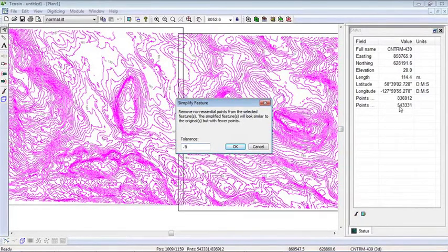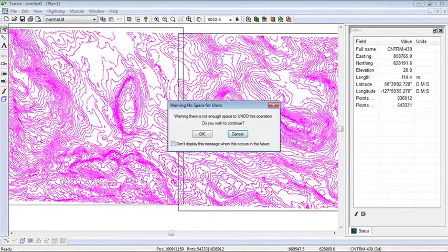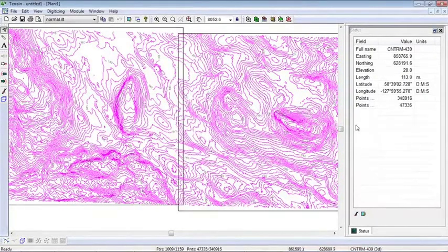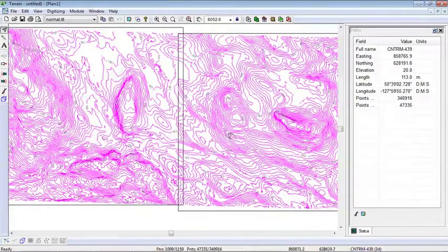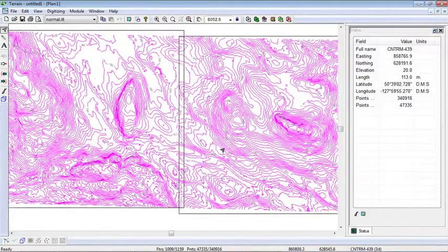Currently, you can see that the point selected is almost half a million points, so the contours themselves are half a million points. After I do this simplify, it's only 50,000, so that actually reduced the number of contour points by a factor of 10, and it doesn't look all that different. Nice thing about that is it draws faster. Okay, like I say, we've got a question here.